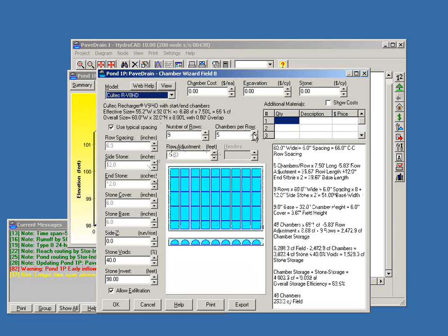That way you've got the benefit of the pervious surface absorbing all of your rainfall directly, plus the ability to augment that and provide whatever amount of storage you choose. And it's very easy to do different scenarios here. You could compare just using stone, if stone is cheap on your particular site, or compare it to using a perforated pipe or an arch chamber product embedded in that stone. So lots of different options, whatever you want to use.